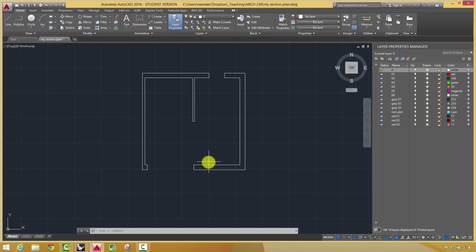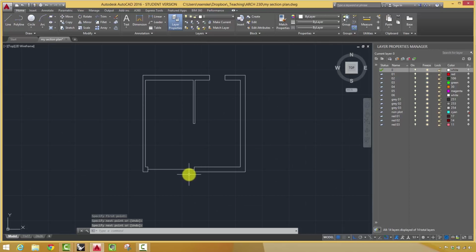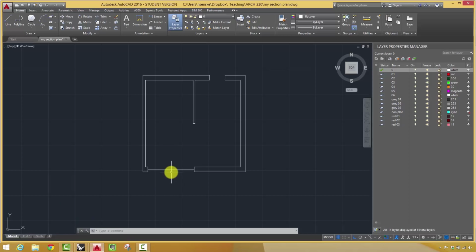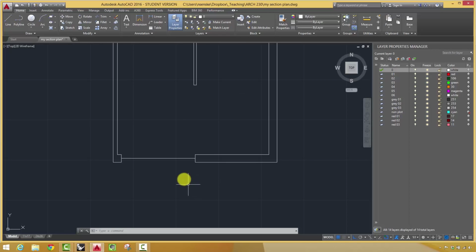So, first things first, though, let's go ahead and make those doors. So again, we're thinking about the center line. This one's this kind of pivot door, and what I did with it was I basically made it so that the pivot is about a quarter of the way into the door, as opposed to exactly in the middle, because I wanted it again to have some kind of hierarchy that this side is more important than this side, and I just wanted it to have some asymmetry. So what I can do to figure that out, I can do a couple different things. The easiest thing to do, since I want quarters, is draw a line from halfway, the midpoint, to the end, and now I would have a snap that is halfway.